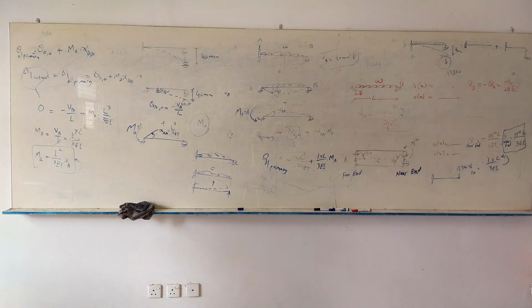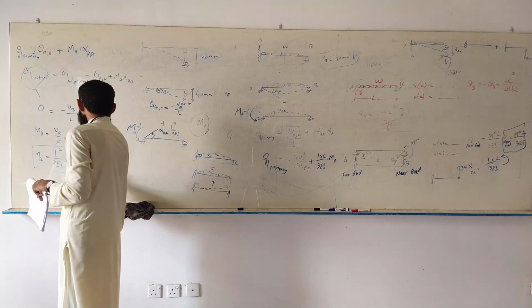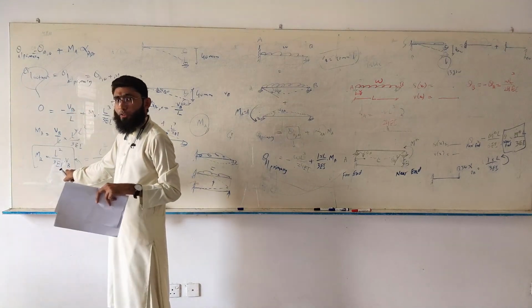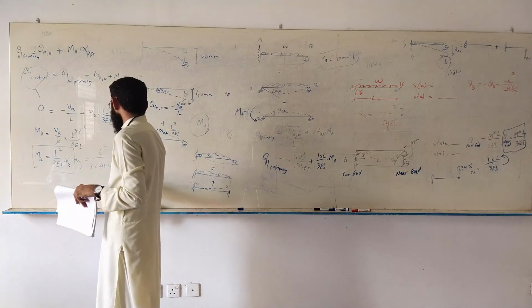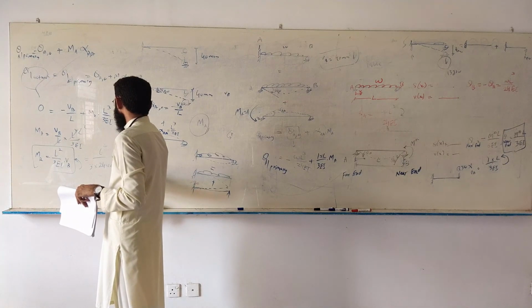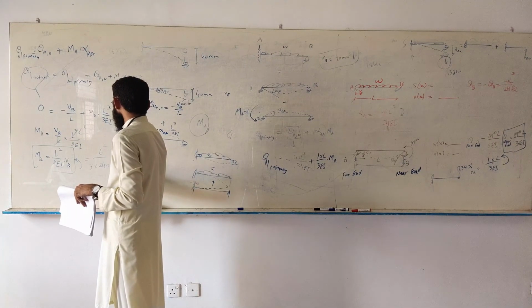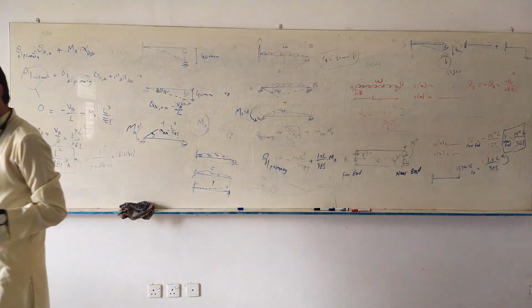But you can still figure it out. Can you calculate this thing? L squared means 6 squared. 3 into EI is 24,000 if you remember, kilonewton meter squared, into VB, which is 40 millimeters, so 0.040. What is the answer?